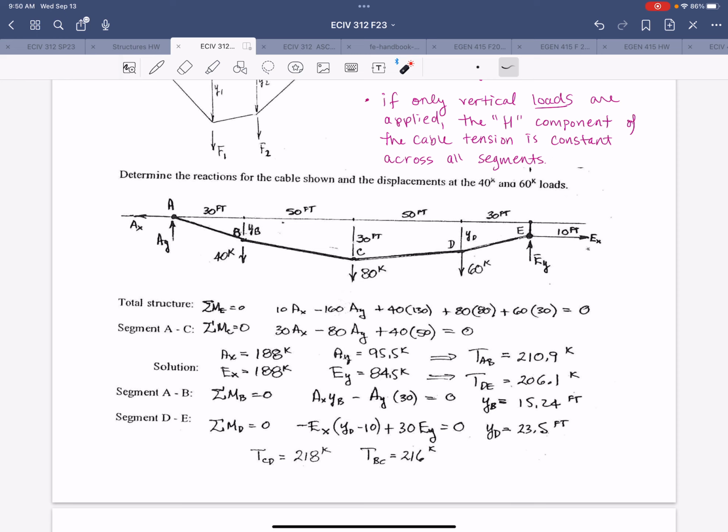So here I show what we would have. We'd have those point loads acting at the joints. The top chord would be in compression, bottom chord in tension. Those diagonals would be in tension, and the vertical web members would be in compression. So I think it's a pretty cool exercise. Next time you're out and about, you see some exposed trusses, take a look at them and see if you can assess how those members are transferring forces through the truss.